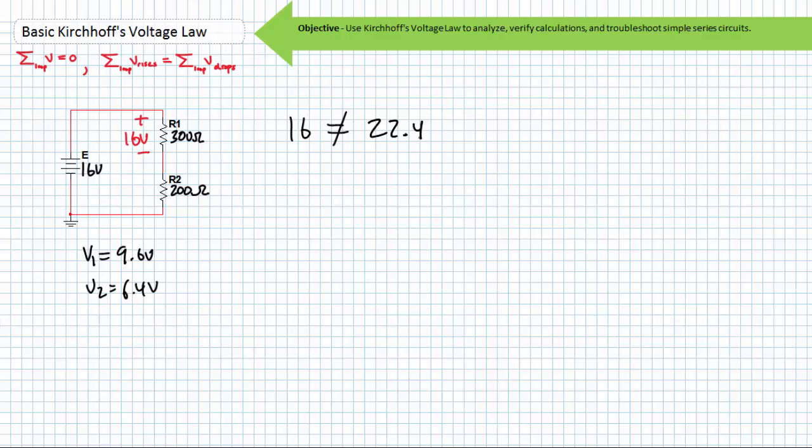A valid answer to this question is as such. Check the supply voltage. If the supply voltage is not 16 volts as required, but rather something higher than 16 volts, it would be understandable that R1 would drop more voltage than expected because it's not the circuit you intended to build.